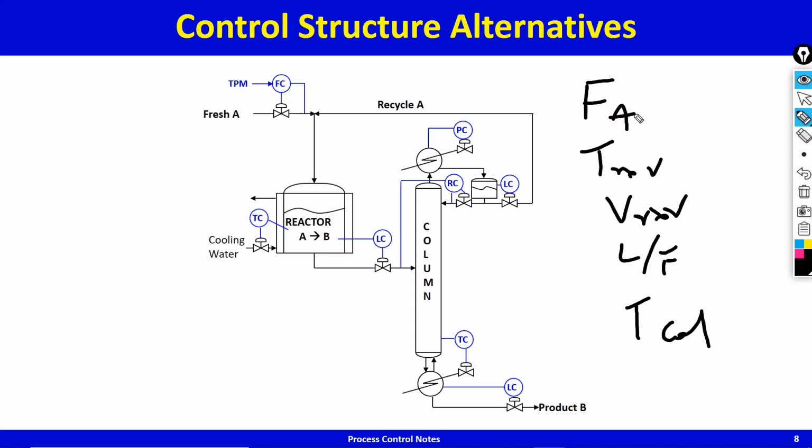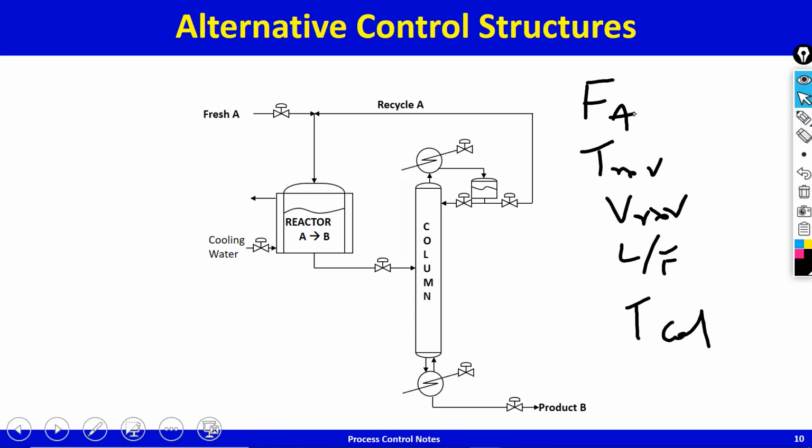Yeah, we can continue. In this case, the throughput manipulator is at the bottoms. So what we have is throughput is being set by the bottoms rate from the column. So we will call it B. Control shift. We'll call it the bottom rate B.